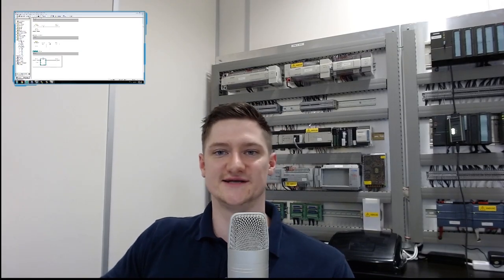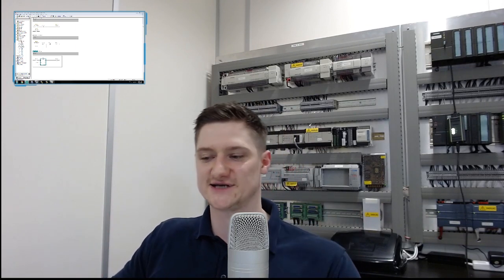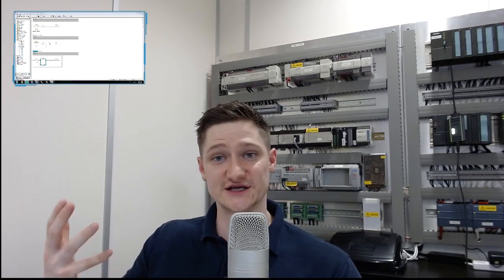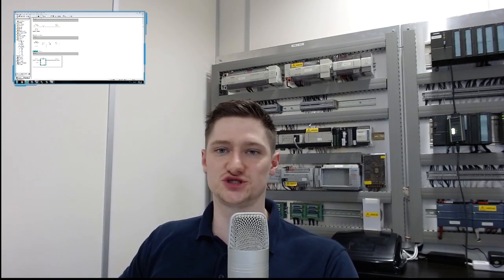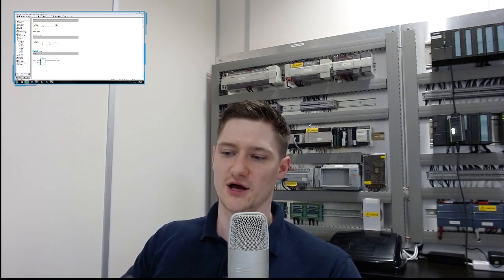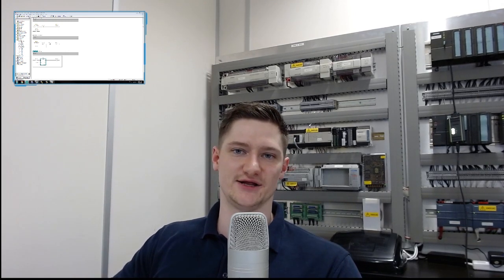And that there, guys, is Siemens timers. That is showing you S5 timers, S7 timers. As I mentioned before, we prefer the S5 timers because everything's in a compact design. And then showing you how we can just use a standard on-delay timer to create all of the other timers available with just a little bit of logic inside of the PLC.